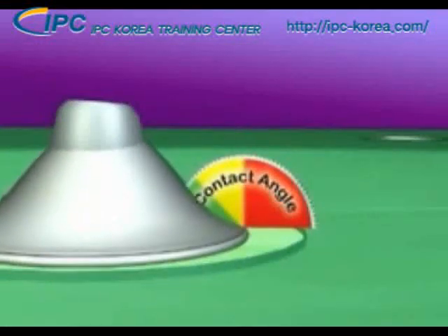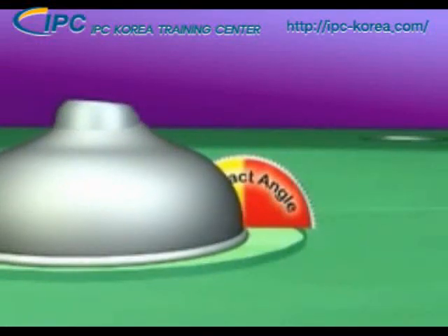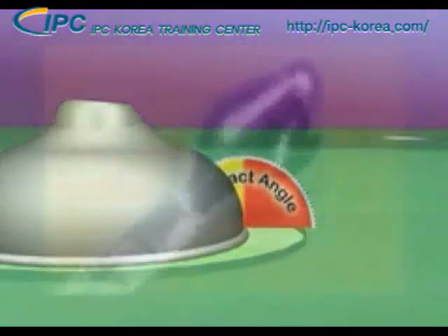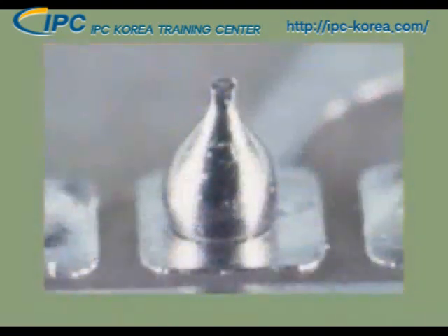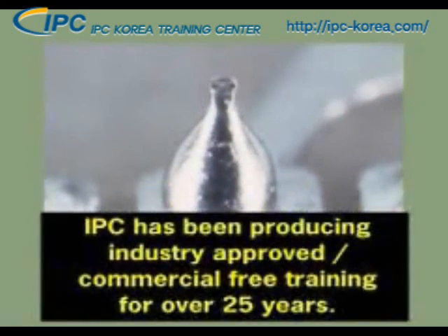The ideal solder fillet will form a contact angle of 90 degrees or less. A contact angle of greater than 90 degrees is acceptable when the cause is the quantity of solder extending over the land. The solder joint is considered rejectable when the fillet is convex and the contact angle is greater than 90 degrees, but solder does not extend over the land.